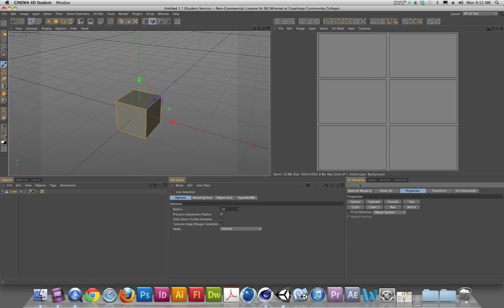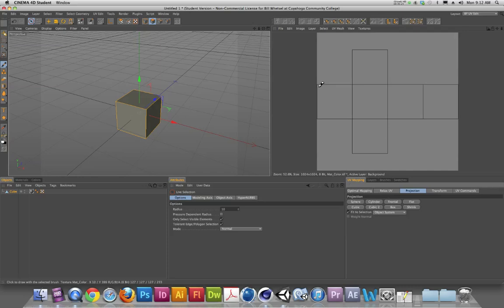And there's some presets over here. If I go to UV mapping, and I'm going to go to the projection tab of the UV map, you can see that there's some basic shapes here. And if I choose cubic, it looks like everything disappears, but if I choose cubic 2, you can see that the cube ends up unfolding, but the texture is one continuous UV map, okay, that's unfolded.